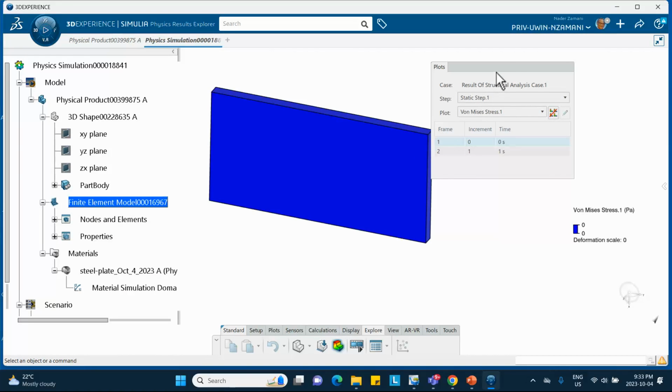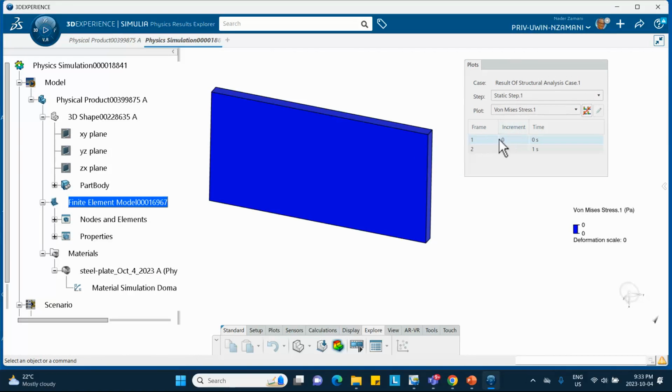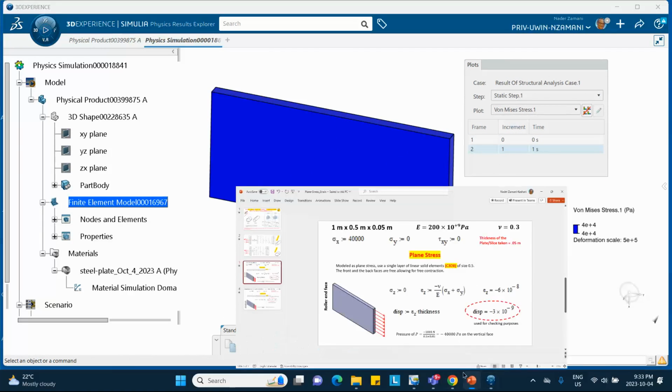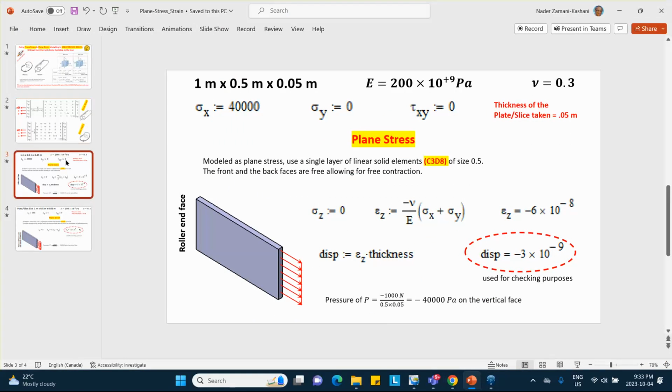So how do we check our stuff? Well, this is before we apply any load, and there is applied load. That does not surprise you. All the same color, all 40,000 psi. That is not something complicated. You apply a uniaxial load here, 40,000 psi. Everything is going to go to 40,000 psi. Now the question, how do we check this number, the displacement?